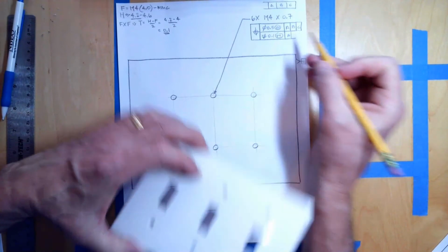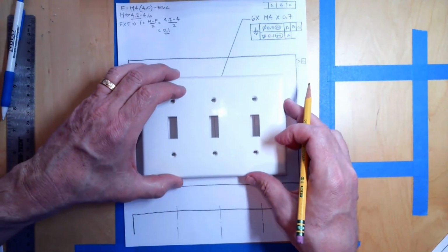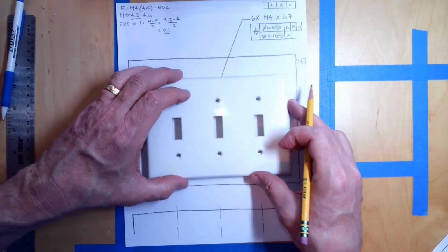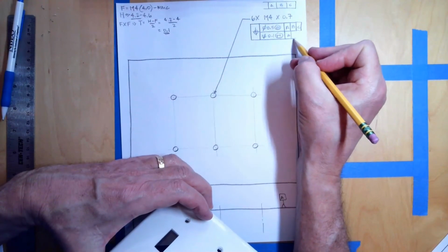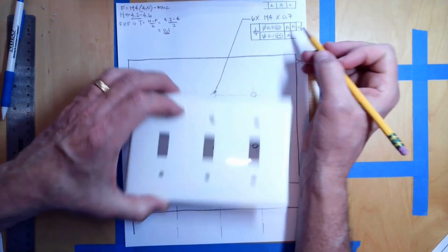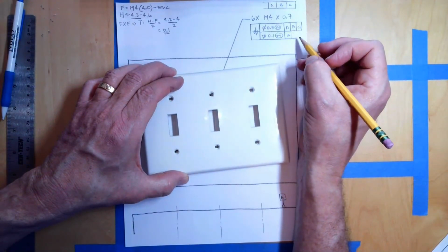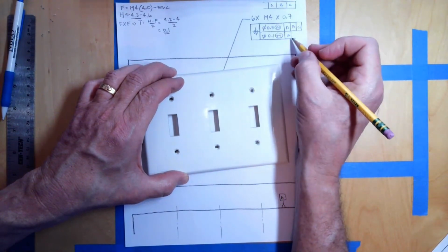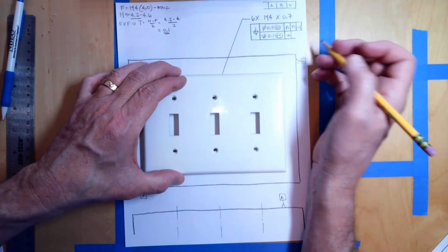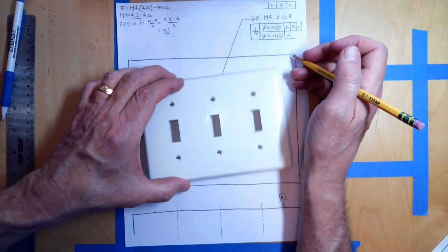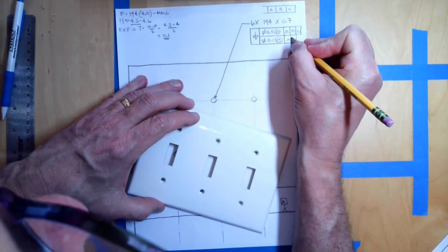If yes, then that's it. If I want the cover plate to not be at an angle, so in other words, it can be 0.5 millimeter up and down, left and right, but it cannot be twisted, then I need to repeat B. If I can tolerate the cover plate being slightly twisted, then I have only A. Now let's say for appearance sake, I don't want the cover plate to be twisted. So I'm going to repeat B right here.